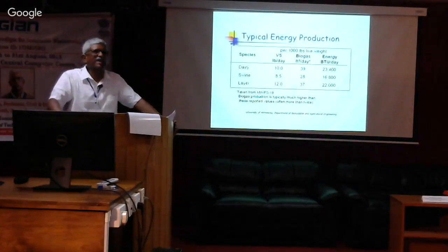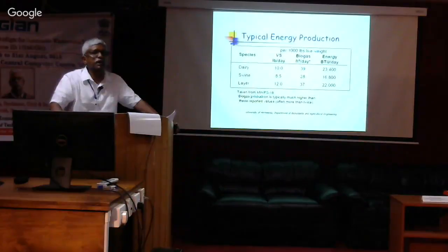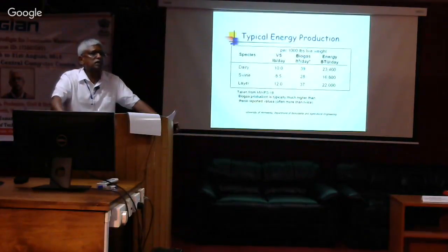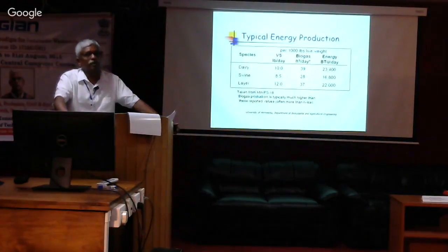And in the slurry, typically, the ones that I'm familiar with have a maximum of about 8% suspended solids. 8% is very high. I mean, 1%, keep in mind, is 10,000 milligrams per liter. So 6%, 7% is pretty common. But the hydrolysis of organic nitrogen to ammonia is very fast. So you are dealing with the nitrogen in the solution.